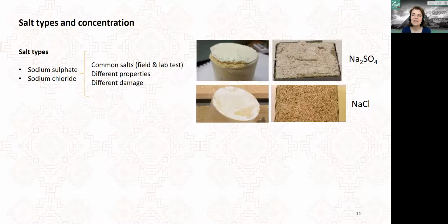Generally, in salt crystallization test procedures, the standard, for example the European standard, considers only sodium sulfate, but we think that the two salts are so different, also in the type of damage they cause, that it is necessary to consider the two salts, and maybe also to consider differences in the procedure depending on the type of salt. Both sodium chloride and sodium sulfate are salts which are commonly present in the field, and they are also sometimes used in laboratory tests.